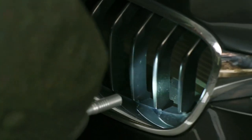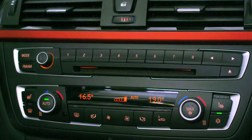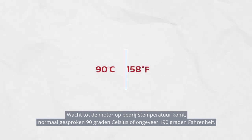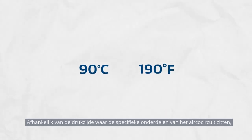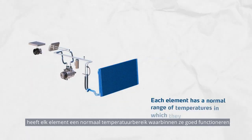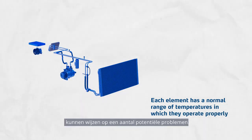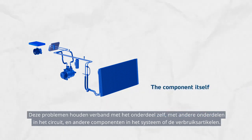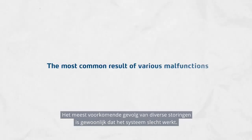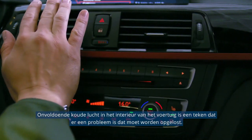module and difficult access. First, start the engine and set the AC on to the coldest air and maximum blow. Wait until the engine achieves its proper operational temperature, which is typically 90 degrees Celsius or around 190 degrees Fahrenheit, and you're good to go. Depending on the pressure side where the specific AC loop components are located, each element has a normal range of temperatures in which they operate properly. Temperatures outside of the normal range, too high or too low, can indicate a number of potential issues. These issues relate to the components itself, other components in the loops, and other components in the system or the consumables applied. The most common result of various malfunctions is usually poor performance of the system. Not enough cool air in the vehicle's cabin is a sign to start troubleshooting.